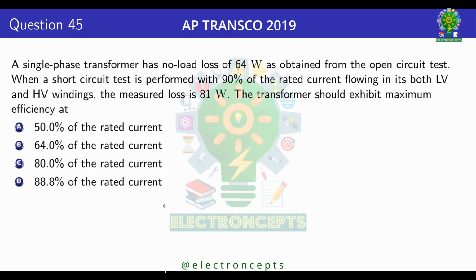Question number 45. A single phase transformer has a no load loss of 64 watts as obtained from the open circuit test. When a short circuit test is performed with 90% of the rated current flowing in both its LV and HV windings, the measured loss is 81 watts. The transformer should exhibit maximum efficiency at what load? We need to calculate the load at which the transformer exhibits maximum efficiency.